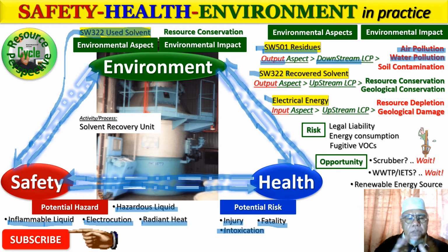And if this residue doesn't go to the incinerator, it may be transported to what is called a secure landfill. Heard of it, right? In a secure landfill, as you know, there is always leachate. And that leachate may find its way into the ground one way or another. The earth is moving. No secure landfill is absolutely secure. Those civil structures can give way after time.